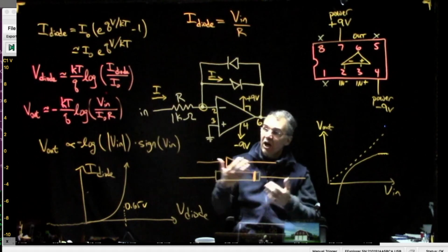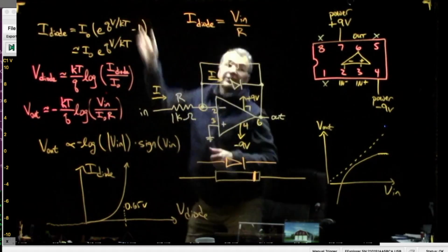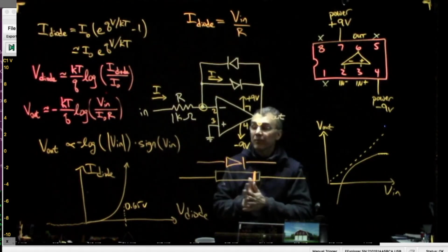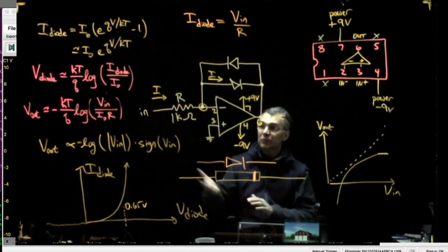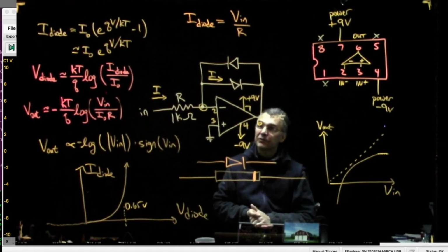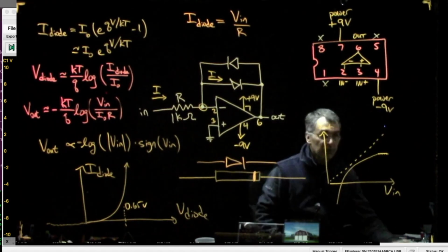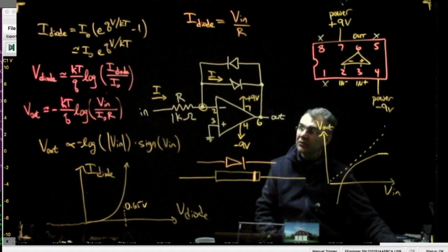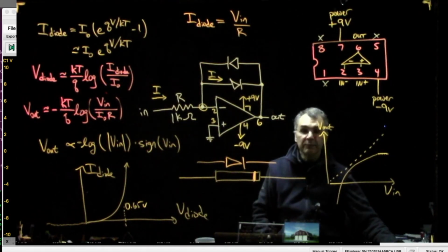The op in op-amp, operational amplifier, really is intended to mean that you can do mathematical operations, because you can do addition, subtraction, and multiply by a constant very easily. You can do logarithms, and you can imagine putting some of these things together and doing multiplication or division. So this is the end of the second of 2 labs where we're basically showing you pretty much straightforward applications of the golden rules of op-amps.